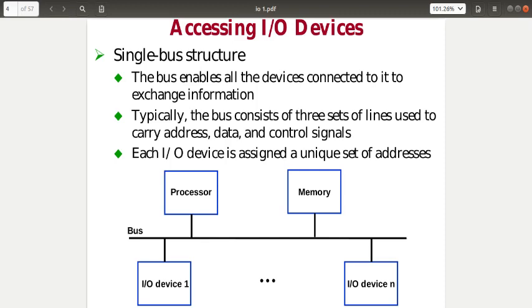So how do you actually physically connect? In the microarchitecture lectures we went through earlier, we considered the concept of something called a data path, right? What was the data path? The data path was the collection of devices or state elements through which instructions and data were flowing, and then there was the control path. We considered the elements, and in between the elements there were lines. We just drew lines to show that this is connected to the other and data is flowing from one element to the other, or control is being sent from the control unit to certain elements, right?